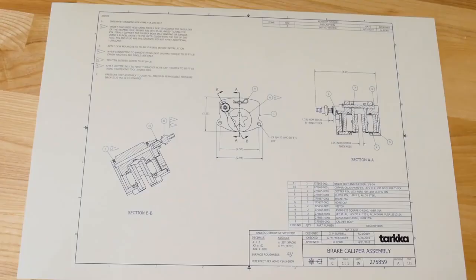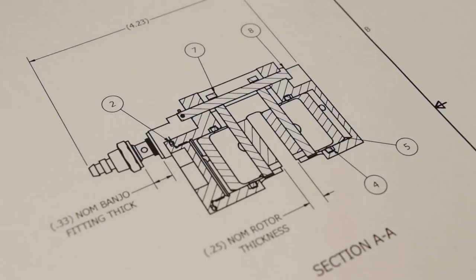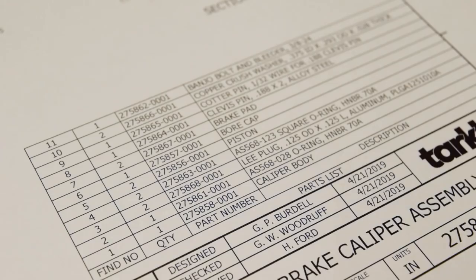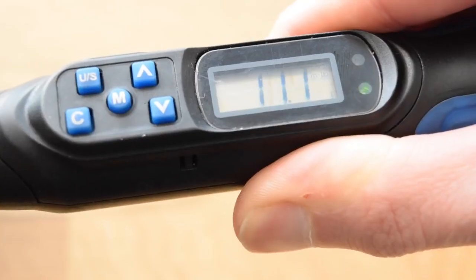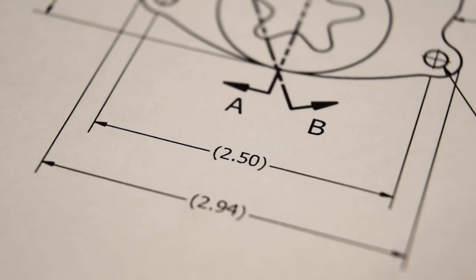Assembly drawings are critical for showing how complicated assemblies go together. Enough views should be chosen to clearly show every component. Parts are often identified with a find number in a bubble. A parts list on the face of the drawing indicates the corresponding part number, description, and quantity required of each find number. Notes can be used to provide information like torque specifications or testing requirements. You may also want to include some reference dimensions for mounting features.